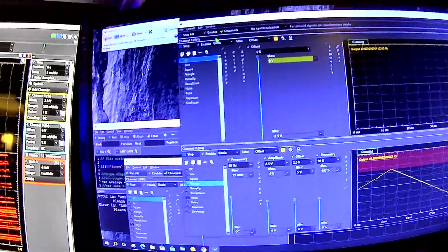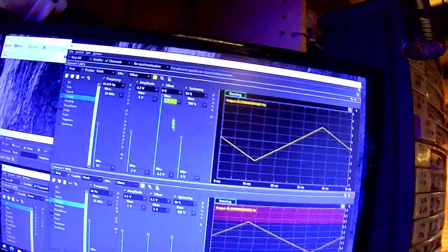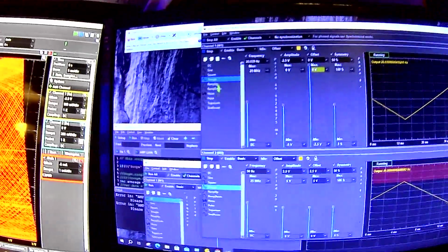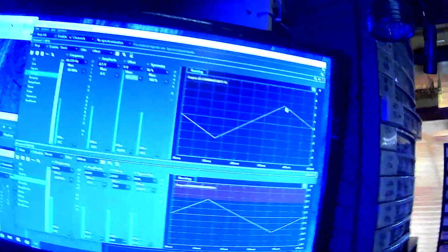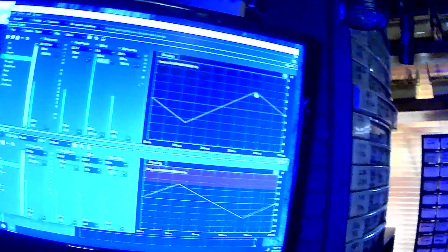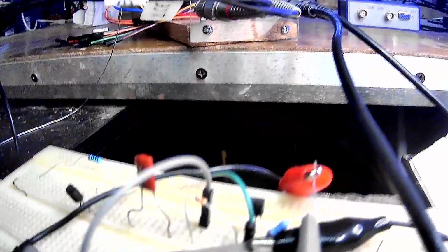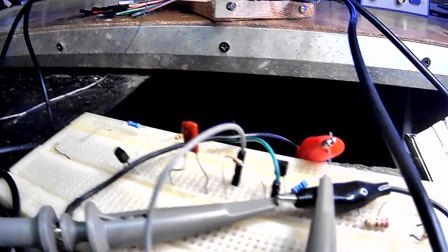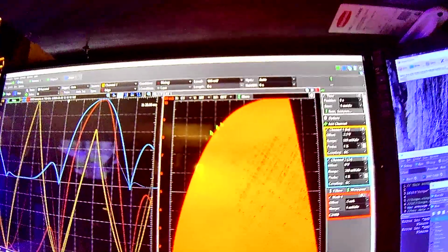But I wanted to point out why I wanted to have another waveform generator. If I go back to, let's say, a triangle wave, well, look what happens. You know why? Because I screwed with that offset, and that's being applied to all waveforms that you can generate here. So now instead of this gate voltage being strictly negative, it's actually going 2 or 3 volts into the positive territory. That's why I put that little 10K resistor in series with that wave generator, in case I accidentally did that. So this shows you what kind of curve you get if it's going into the positive bias region.